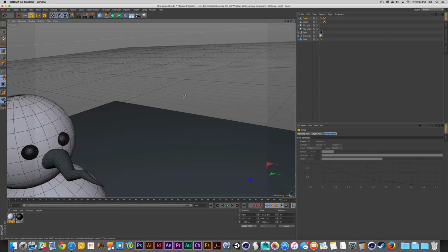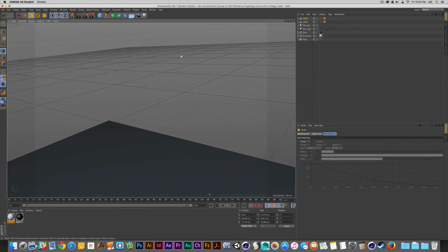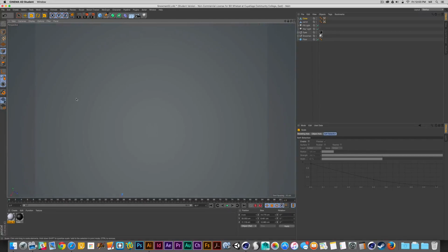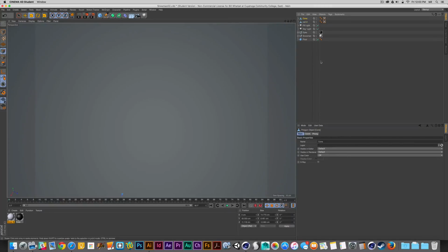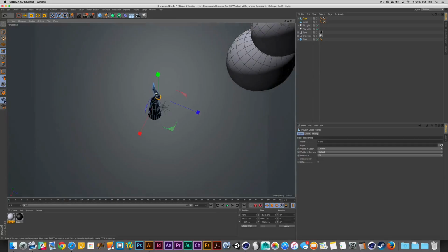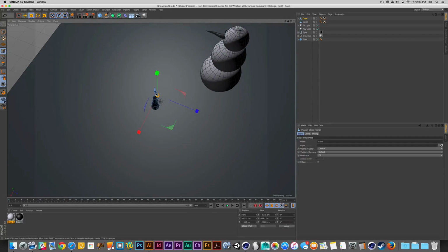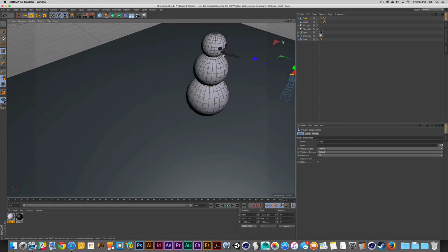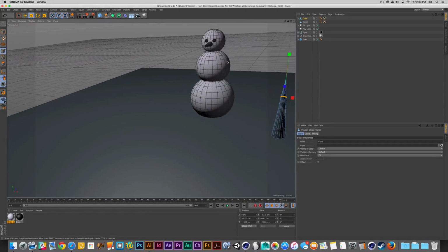In the event that you get lost, okay, and you kind of have a funny click and say, I have no idea how to get back, or I'm completely disoriented like this, what I like to do is just select one of the objects in the object manager, and as long as your mouse has focus over the perspective view, you can usually tap the O key, which will frame the object. At that point, we'll just zoom out and see what we're looking at. Just a quick, easy way to get back to a frame of reference.